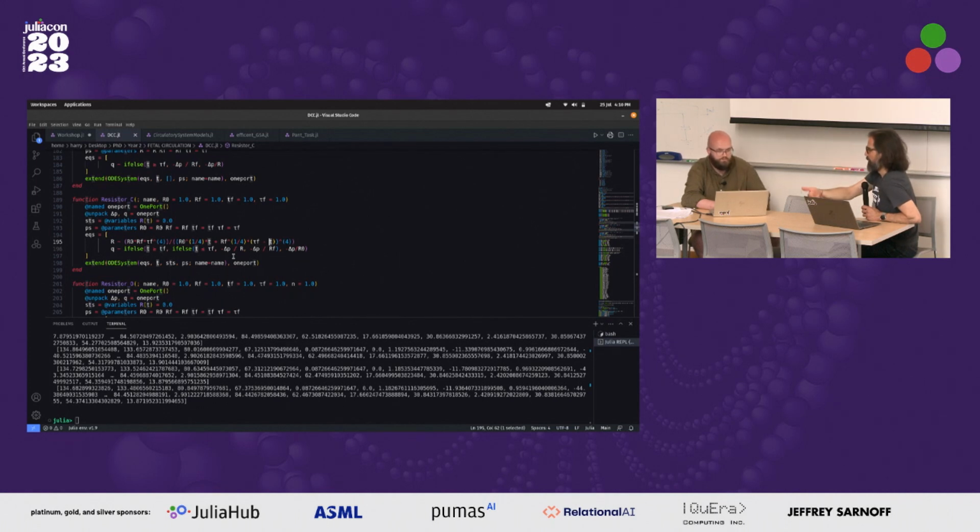I mentioned earlier that you can also do it as an external function if you want to change that a lot. An example would be the driven force or driven flow equation, which takes a function, like I showed in the introduction, and which Harry used earlier, where we had driven flow. We have the maximum Q multiplier, and then we give it a function that we usually define between 0 and 1, which gives you the flow shape. That's an external function that's called. So for external functions, if you look at the driven flow element, that is how you can do external functions for any of these internal parameters.